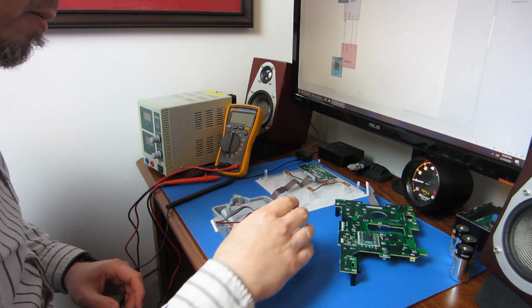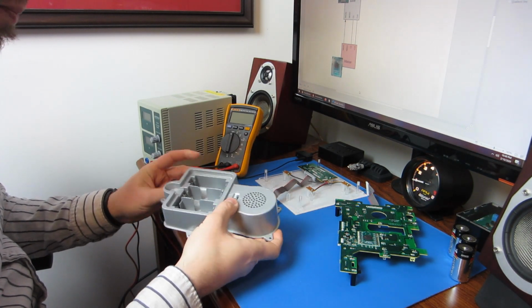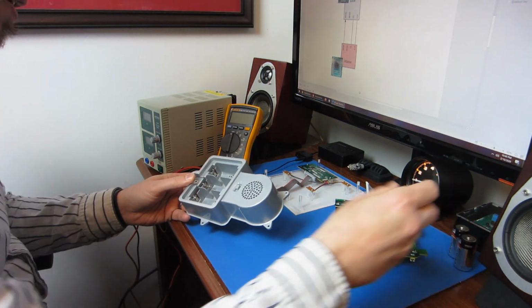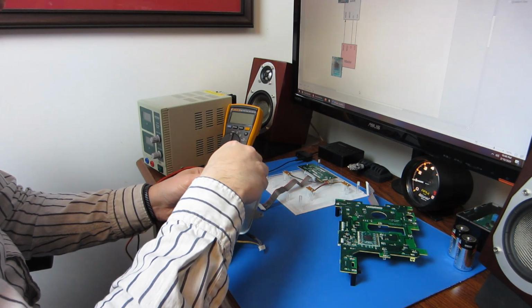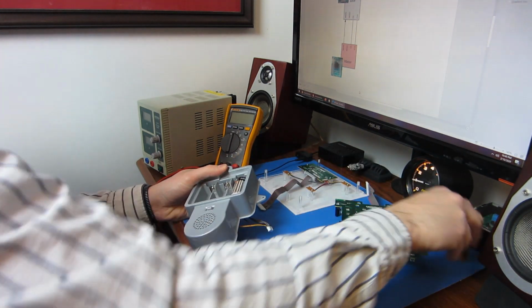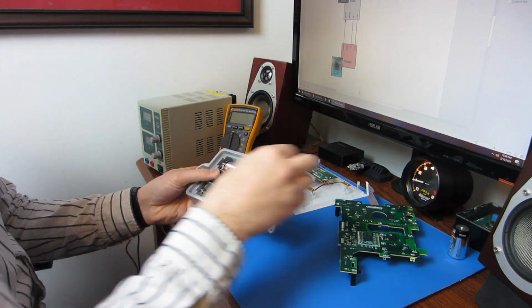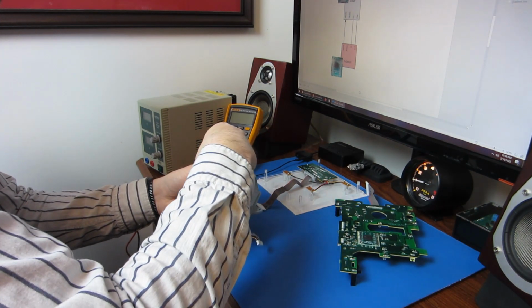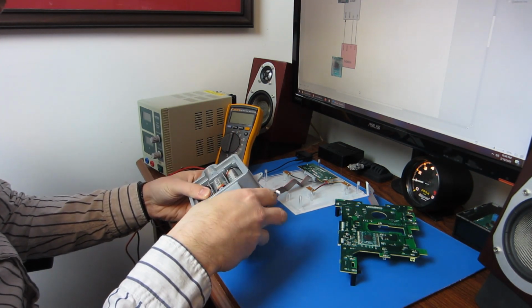The boards are normally powered through this connector using batteries in this battery holder. But for convenience sake, I'd rather power everything off my benchtop power supply. So the first step to getting it powered on the bench is to figure out how much voltage to give it. It runs on 3 C batteries, and they're each 1.5 volts.